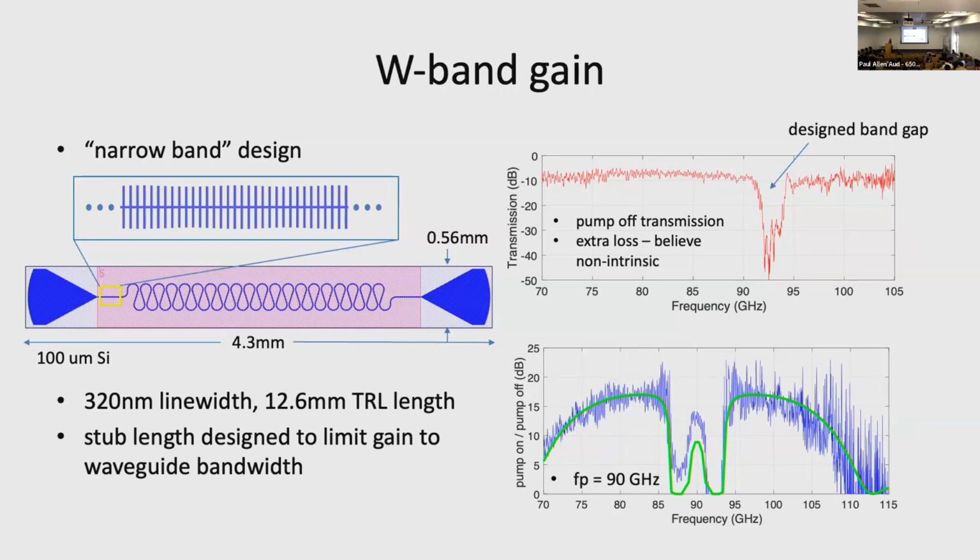For the actual gain, you'll have to subtract the about 8 dB of loss that we had in that case. The loss for this device, we think, was coming from an error that we made in the housing. We had not machined an air channel below where the device sits in that case, and we think that the fields from the transmission line were seeing the copper housing.